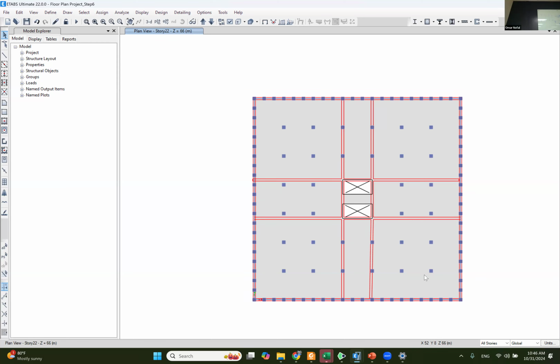So I believe I covered everything about the modeling. Maybe over time, if you are stuck with the bracing, it is easy. You view the side view and you just keep drawing the columns story by story like this to make the bracing. But if you are stuck with this, I can definitely help you with that. And it's a bonus, so you guys are all covered.